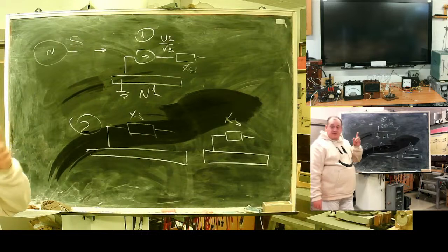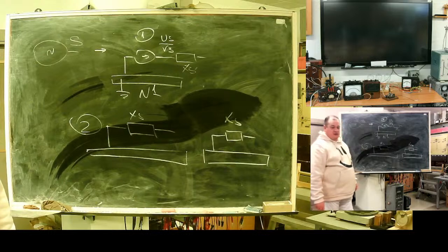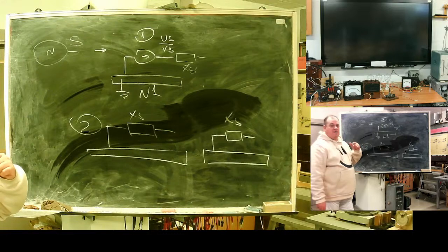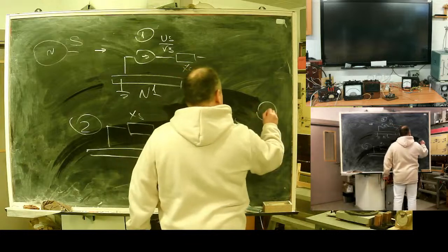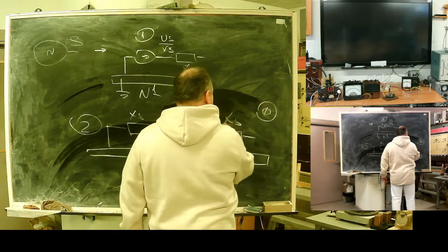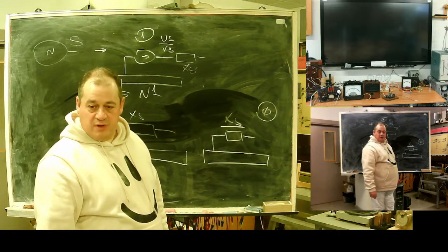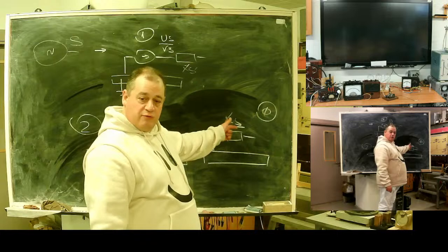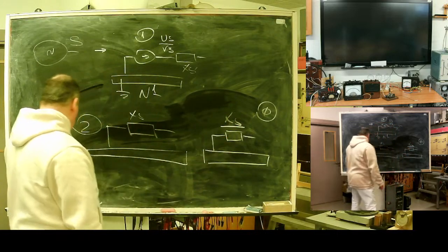One possibility: when people from the network operator calculated this equivalent resistance, they may have taken into account the connecting line. If this line is long enough, you will see an increase in zero sequence. So if you have a paper from the network operator, check what they calculated. Maybe they will give you a bit higher resistance.